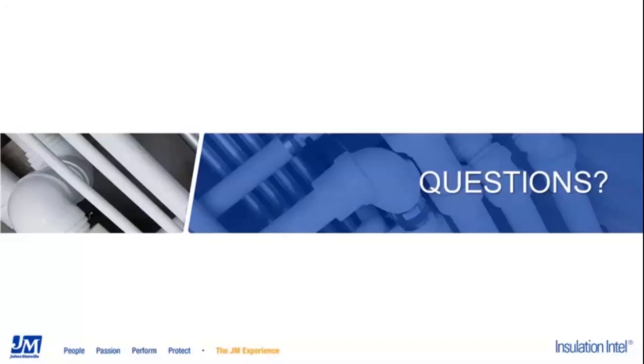So I would say more importantly, what is going to offer the protection against the corrosion is going to be the polyfilm moisture barrier that is heat laminated to the inside of our metal jacketing. Both of our aluminum and our stainless steel jacketings comply with ASTM B209 for aluminum and A167 for the stainless, respectively. But I think more so for the corrosion, it's going to be the polyfilm moisture barrier.